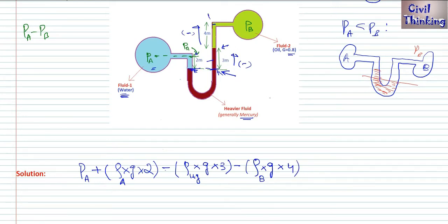We are here, right? Now if you draw a line here, you see here is the same fluid, fluid B, here is fluid B, until we reach the pipe inside. Because they are the same fluid, the pressure at this point is the same as the pressure at this point, means we have reached PB, pressure at B.